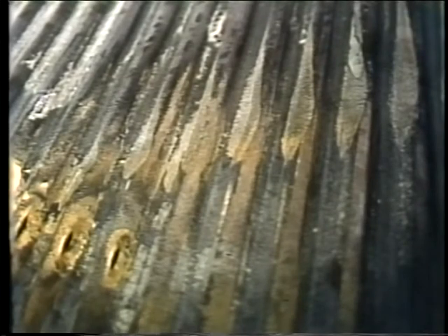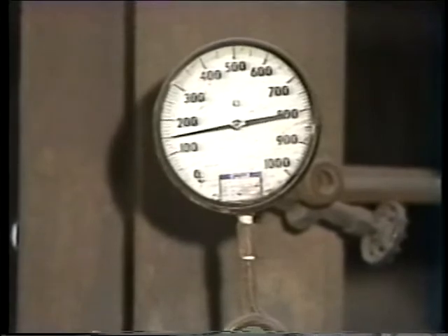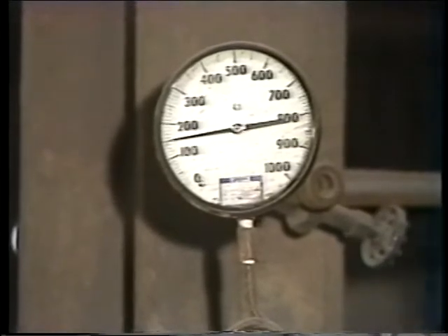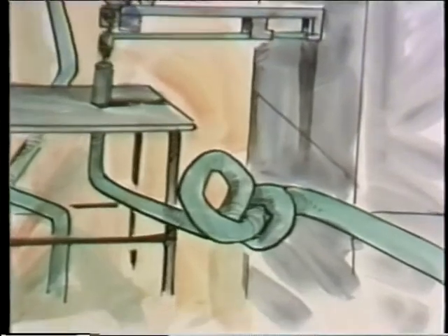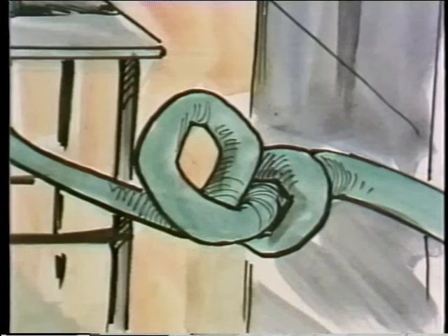Improper blowing pressure can result in damage to the boiler or the soot blower if it's too high, because it might contribute to erosion of boiler tubes or even erosion of its own element. If it's too low, the soot blower won't do an adequate cleaning job because it can't blow away deposits strongly enough. The source of the blowing medium may be where a problem will occur, or there may be leakage somewhere else in the soot blower system.